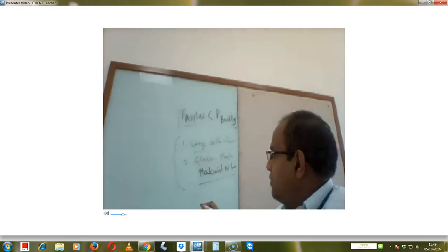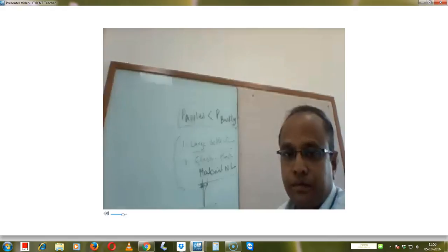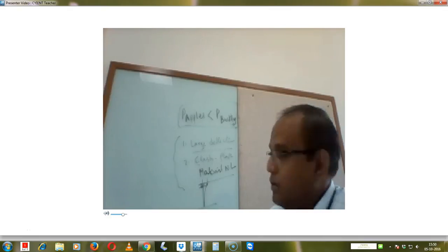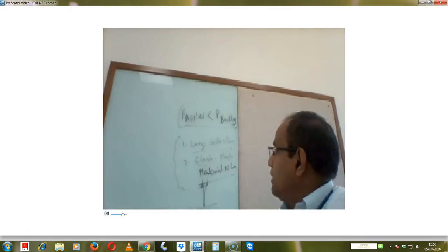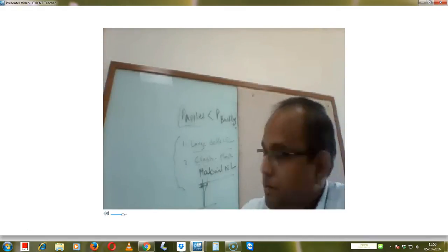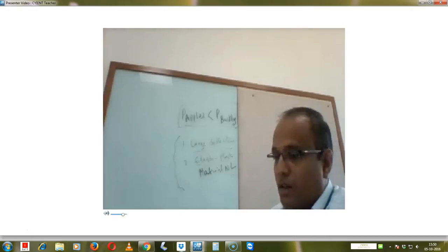That means when you try to solve any model with this type of loading, there should always be a small off-load, so that it will try to deflect in this way, and the buckling phenomenon can be initiated. So this is a nonlinear buckling analysis. Okay, and I would like to give more information on nonlinear buckling analysis.